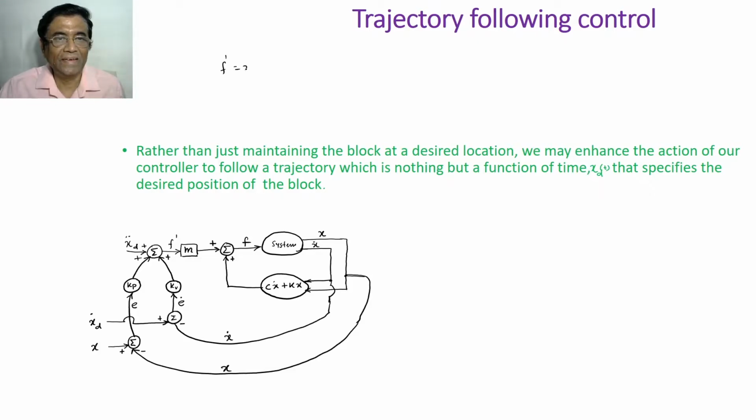So it's controlling just like this, and then you made servo control, x double dot plus kv x dot plus kp x, and then you made this equal to 0 by defining this control law, minus kv x dot minus kp x, like that.